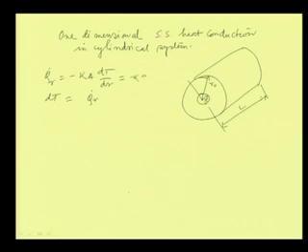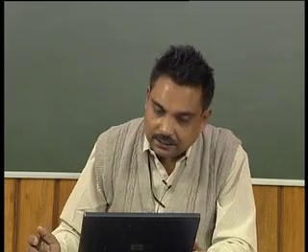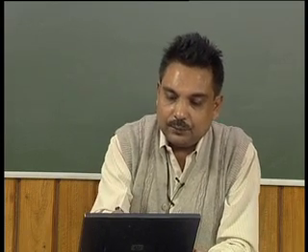The area is equal to 2 pi r L at any point r. This is the surface area through which the heat will be conducted. And one thing we should understand is that the heat conduction surface area is perpendicular to the direction of heat conduction. So, 2 pi r L into dT by dr.